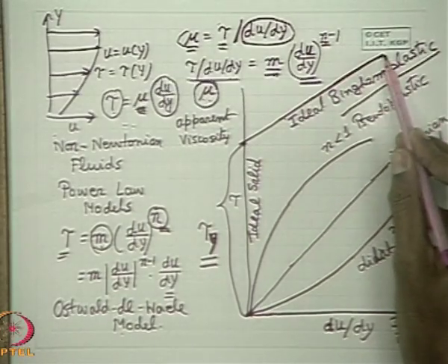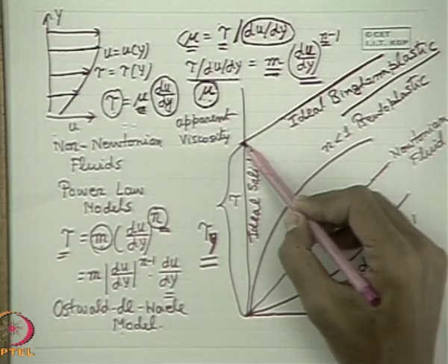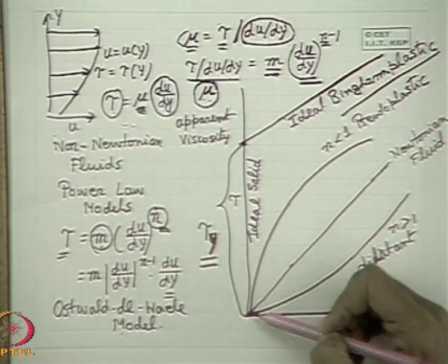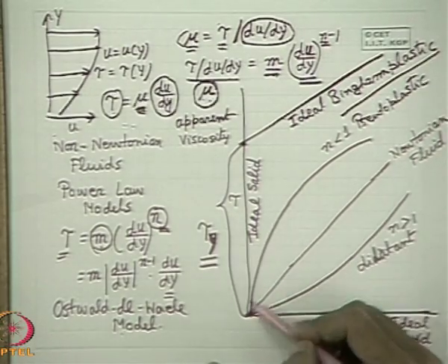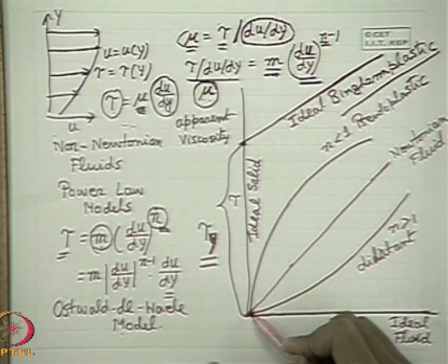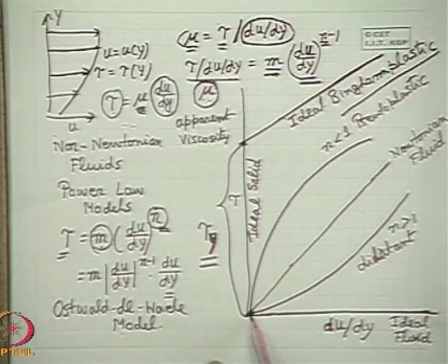But there is a little reservation in calling this class of substances a fluid. This is because the curve doesn't start from the origin. You know that the physical significance of any curve, either linear or non-linear, starting from the origin is that under an infinitesimally small shear stress, the liquid starts flowing.